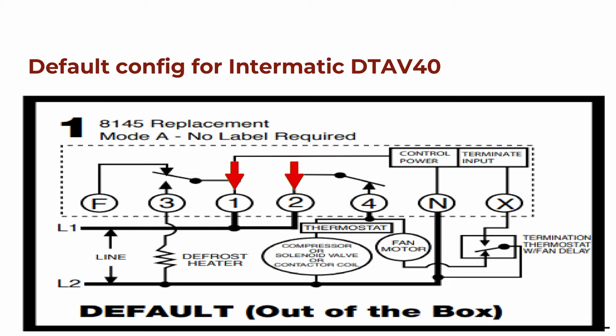But you could have a situation where perhaps this is a different circuit coming in, or there are other configurations where that breaks, such as this 3 here. It's just a different control scheme. And we have terminal 4 here, which is responsible for delivering power to the compressor. So in a self-contained case, the compressor would be sitting up on top of it. So we would need this contact closure to provide power to a thermostat that then controls power to the compressor. So there's a thermostat in this diagram in series with the compressor to control that locally at the compressor.